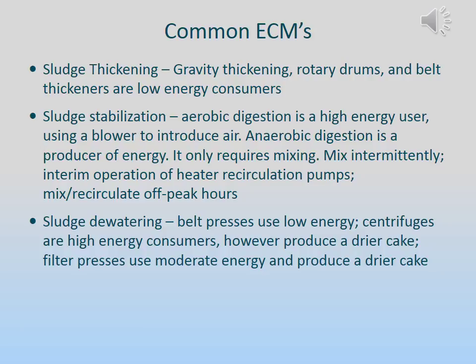Anaerobic digestion is typically a producer of energy. It only uses energy when mixing, which the process requires. Consider mixing intermittently or interim operation of heater recirculation pumps. Mix and recirculate during off-peak hours.